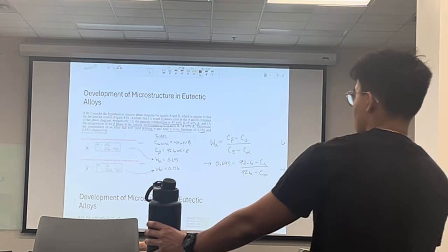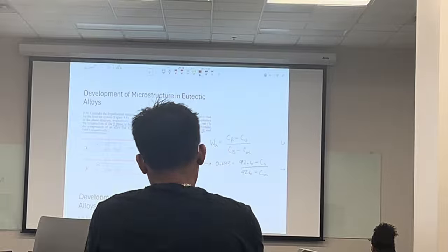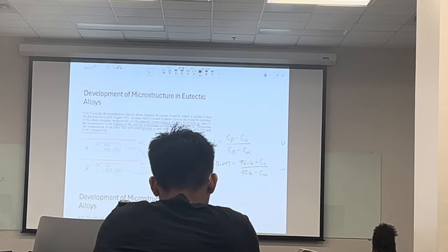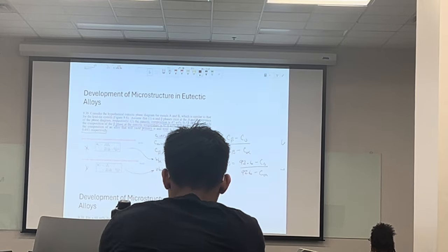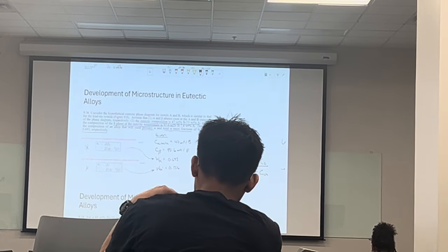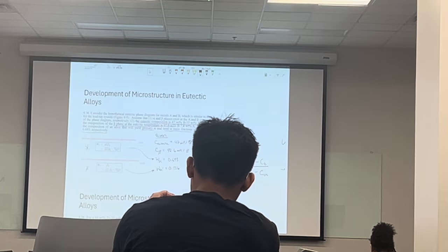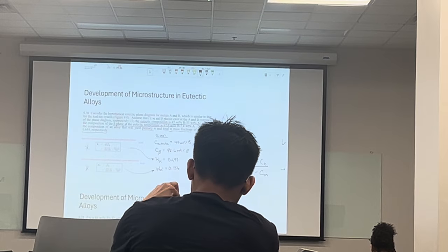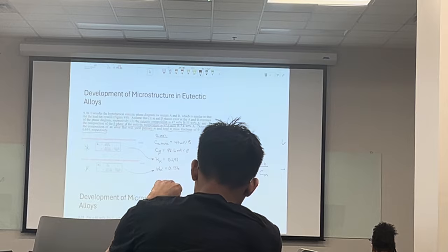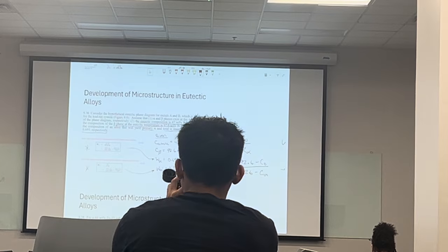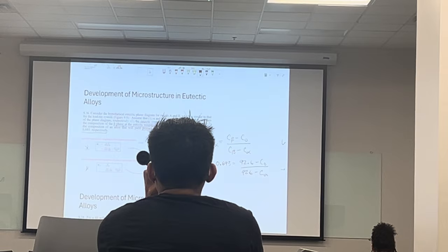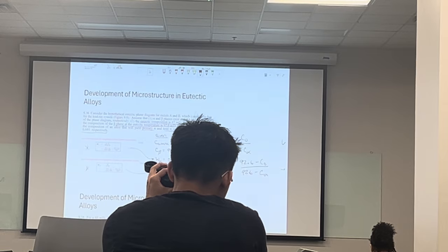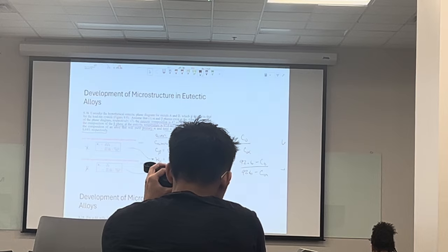And then the key information that we underline to help us outline what's going on in the problem is the eutectic composition, that 47 weight percent of B, and the beta phase at the eutectic temperature, which is that guy, at 92.6 weight percent. So we wrote those down. We also wrote down our primary alpha and total alpha mass fractions, respectively. So those two are down there.